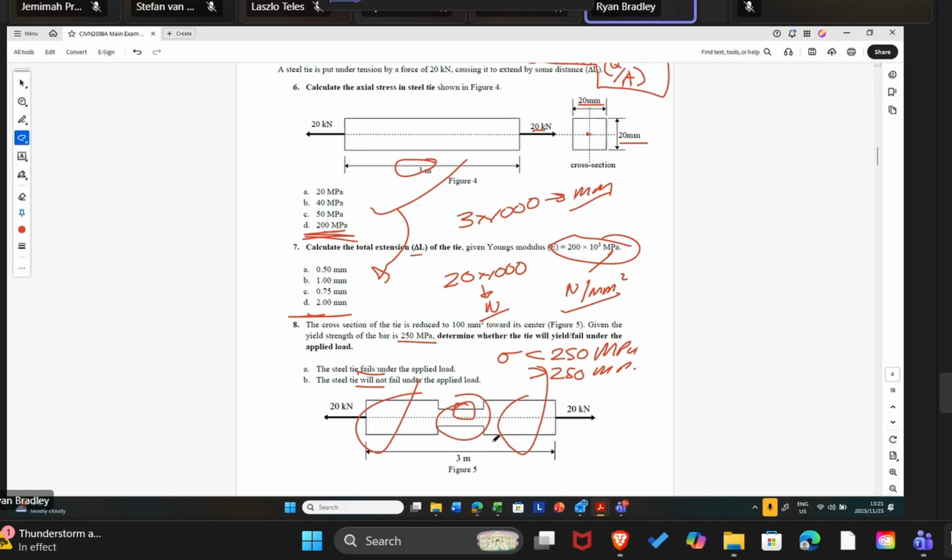Why? Because we know that stress is directly related to area. So the load here is constant. We pull with this load, which means the load is 20 here, it's 20 here, it's 20 over here. It's 20 throughout this section. So the stress is going to be greatest where the area is smallest. And we know this by inspection, right? We know from our lives, it's obvious to us that it's going to fracture or snap here in the middle.